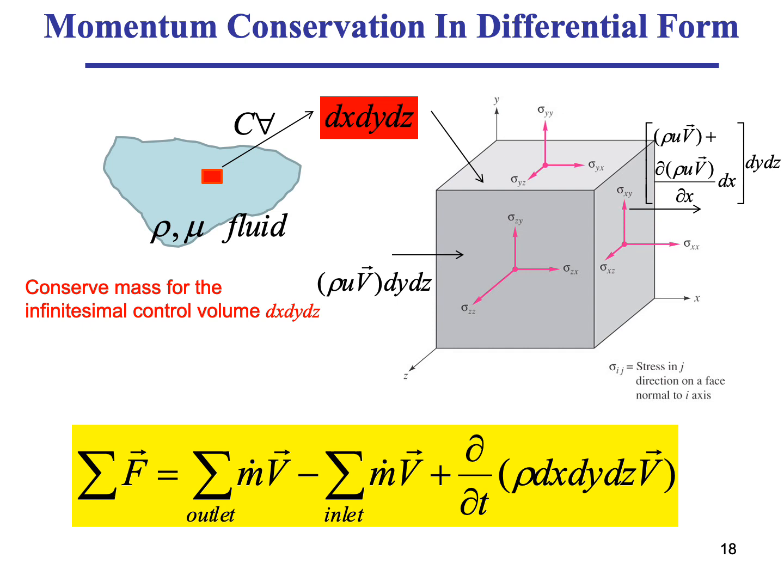So here's what we just said. Each one of those 6 faces would have 3 stresses on it that we will come to later. And in a similar fashion, the stress is one property of the flow, so if I know the stress at location x, I can predict the stress at location x plus dx through the Taylor series expansion.